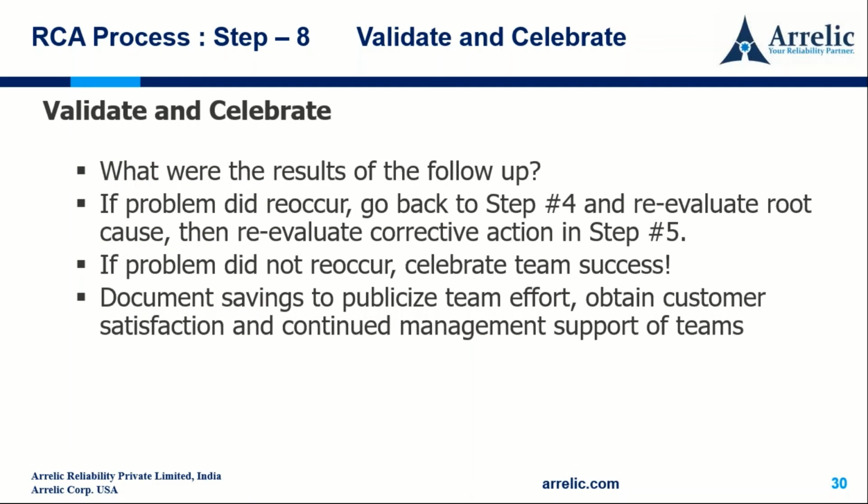Validate and celebrate. What were the results of the follow-up? If the problem did reoccur, go back to step 4 and re-evaluate the root cause, then re-evaluate corrective action in step 5. If the problem did not reoccur, celebrate team success. Always good to celebrate, encourages the team to be successful again and again. Document savings to publicize team effort, obtain customer satisfaction, and continued management support for the teams.